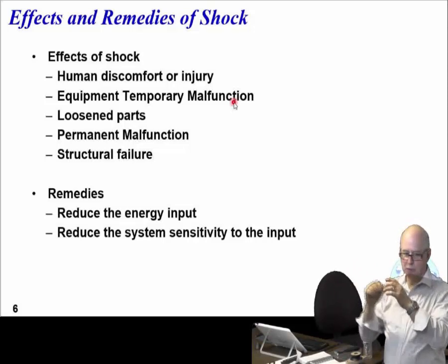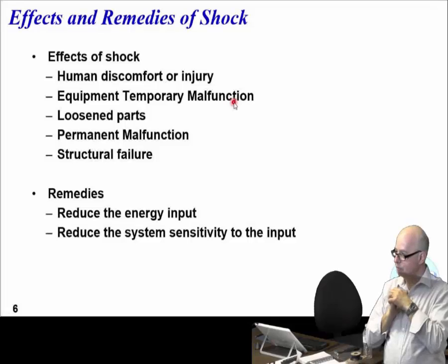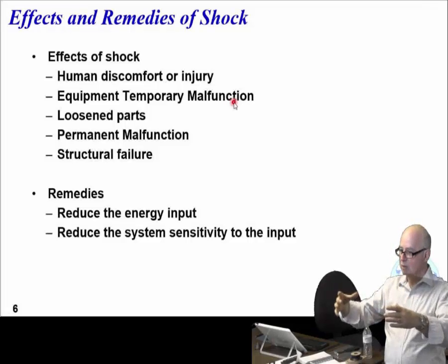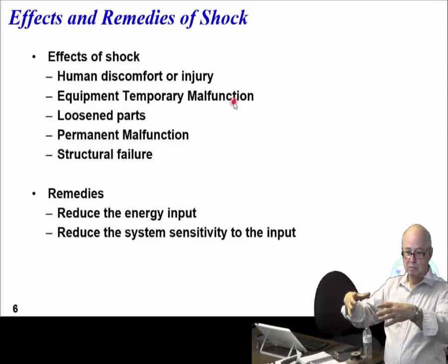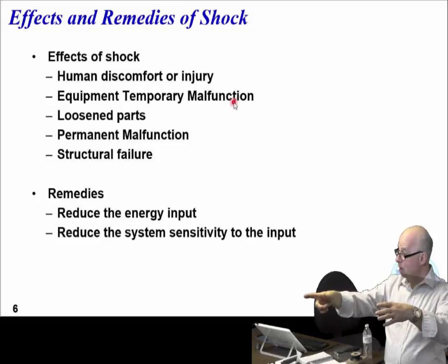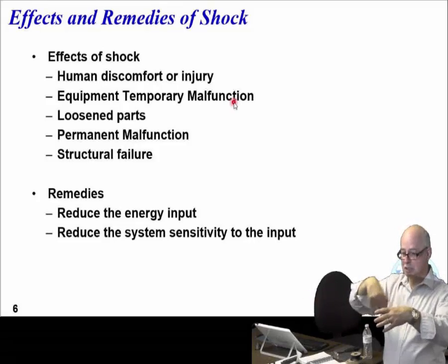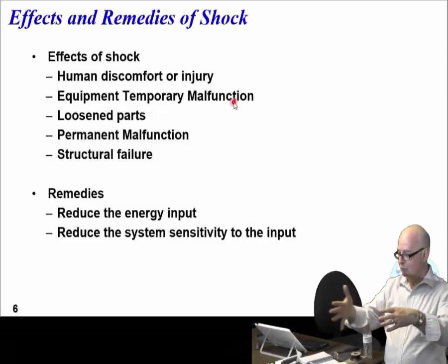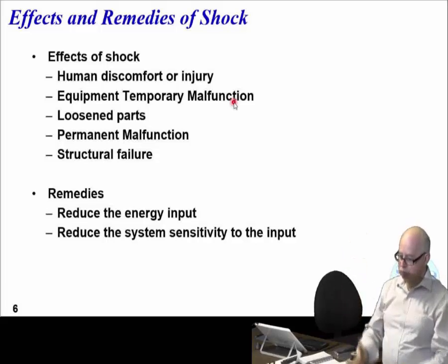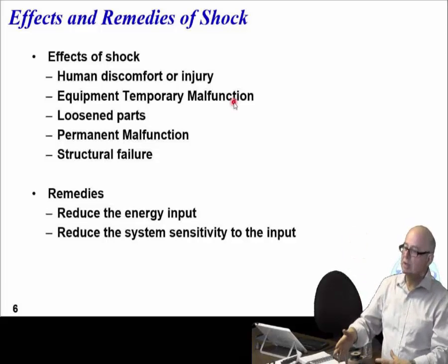And the way they did it was to put an accelerometer into the drive. That little accelerometer just sits there, and if it detects free fall, it goes, uh-oh, stop. And it doesn't stop the drive, it retracts the heads, because you can't stop the drive. So it just leaves the drive spinning, it retracts the heads. Boom. Okay, back to work.